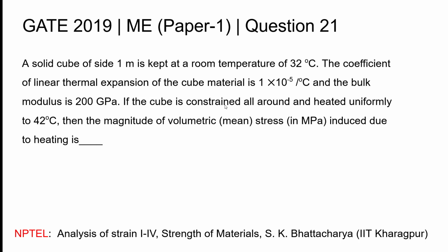Hi all. Today we are going to see a question from GATE 2019 Mechanical Paper 1. Question number 21. A solid cube of side 1 meter is kept at a room temperature of 32 degrees Celsius. The coefficient of linear thermal expansion of the cube material is given and its bulk modulus is given. So if the cube is constrained in all directions and heated uniformly to 42 degrees Celsius, what is the magnitude of mean volumetric stress in MPa induced because of heat?